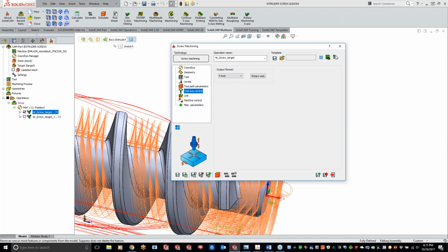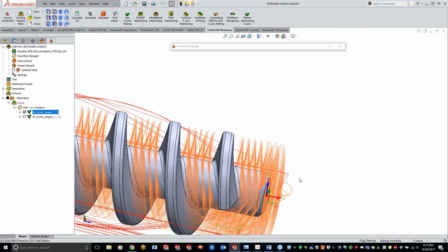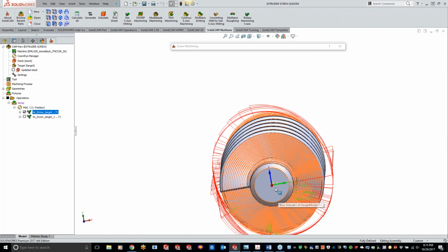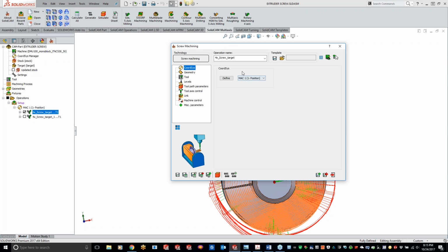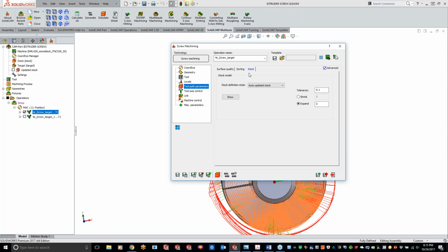Oh yeah, so the circle is based off of the center of your circle right here, or I'm sorry, your XYZ origin point right here. So it's going to be all based off of your coordinate system for that particular coordinate system. So if you guys are running Mach 1, Mach 2, Mach 3, whatever you choose for your coordinate system right here, is going to be based off of your stock right here. If you're doing that bounding circle, is that what you're asking there, Ronnie? Okay, perfect.